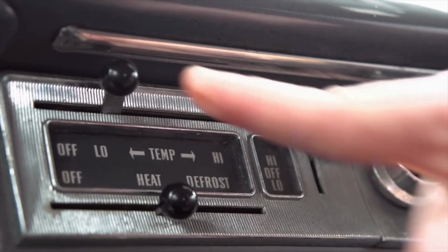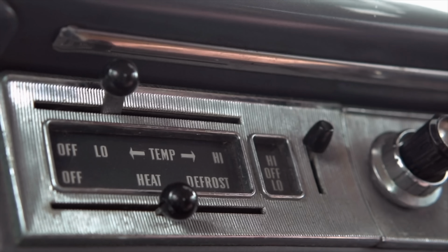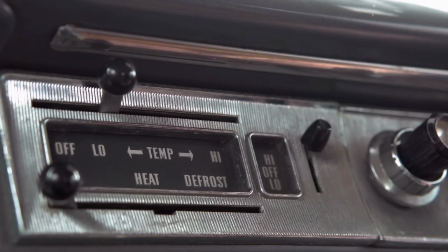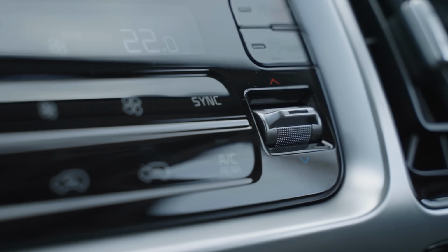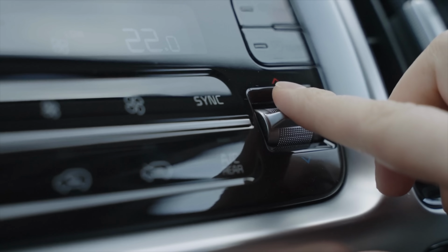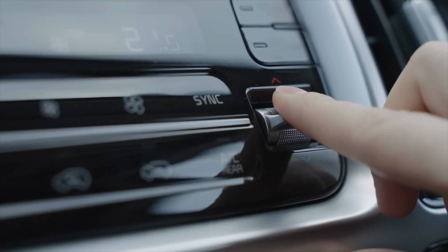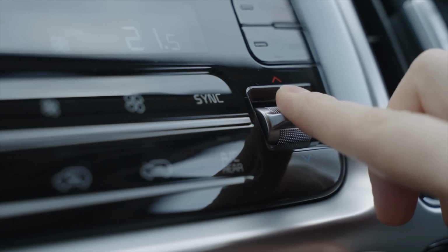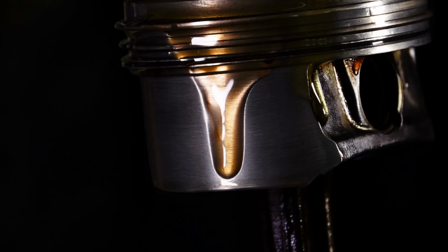Defrost for 10 minutes from time to time to prevent mildew and moisture buildup. Turn on the air conditioner at least once a week for 5 to 10 minutes. Set it to maximum power at the coldest level. This will help ensure your compressor continues to operate at regular gas pressure levels and spreads the oil internally of the system so it's lubricated correctly.